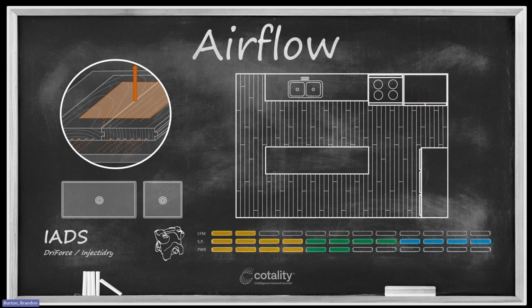Now, to compensate for the air that is moving underneath this floor, and here's the key, there has to be somewhere for air to travel down and underneath the floor. And one of the most common mistakes that's made when installing any form of inter-air drying system, it doesn't matter what type it is, is that we have to understand that there has to be a pathway, right? That pathway has to have an inlet to allow air to enter, and then the side that we're pulling air from.